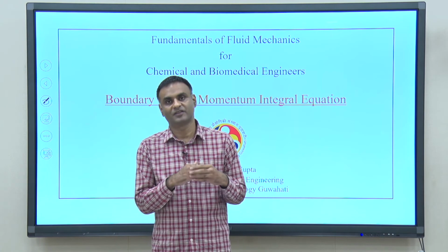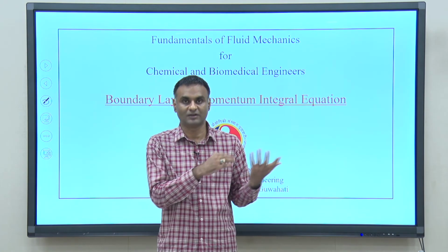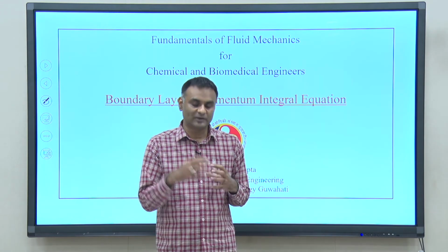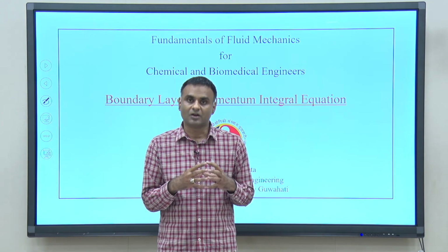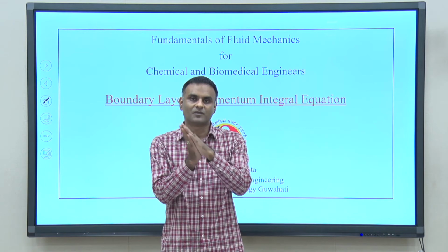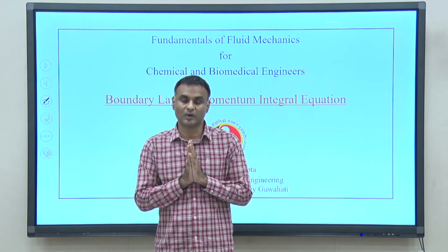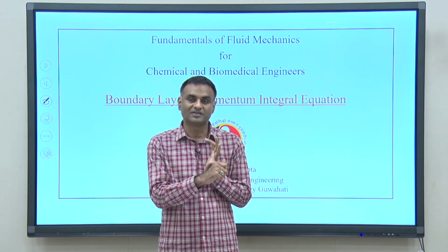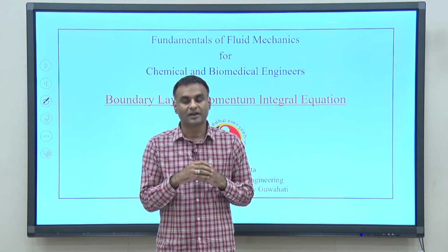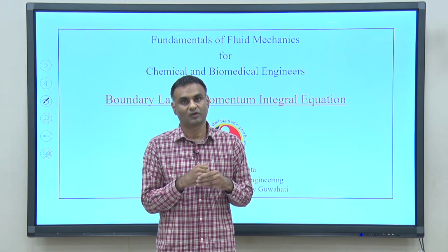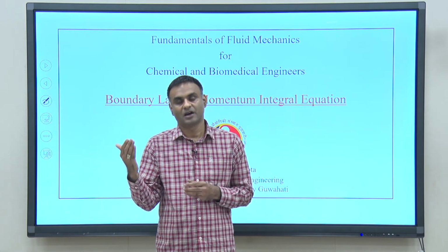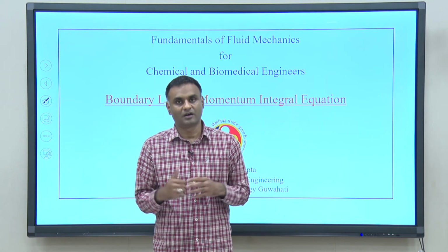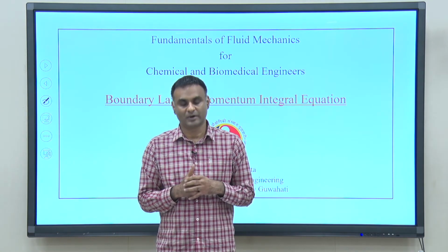boundary layer region in different ways: boundary layer thickness, or what we call disturbance thickness, momentum thickness, and displacement thickness. Then we looked at the Navier-Stokes equation for an incompressible steady two-dimensional flow over a boundary layer, and simplified the Navier-Stokes equation so that we can find the solution of these equations to find the velocity and flow profile in the boundary layer.